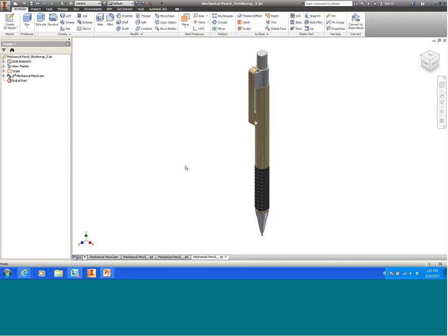One little workaround is that prior to creating your shrink wrap feature, prior to selecting that command, you could suppress or change the visibility of any component in the assembly before you execute the command. Then whatever's visible on the screen will be created in the shrink wrap. So that is one little workaround to removing specific components instead of trying to figure out all those percentages of visibility and percentages of size.